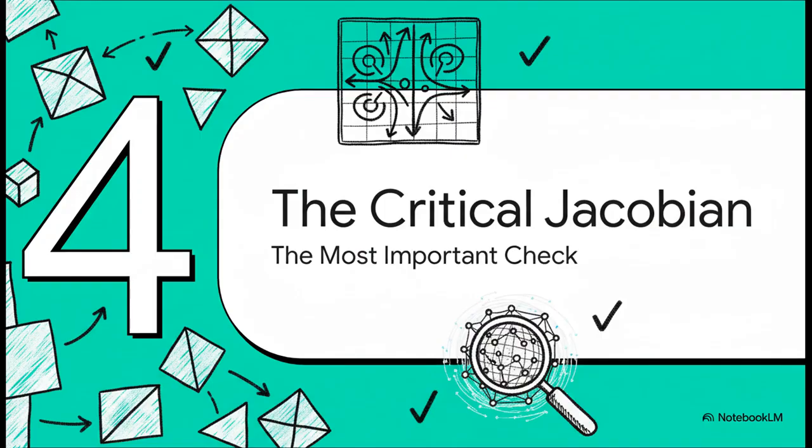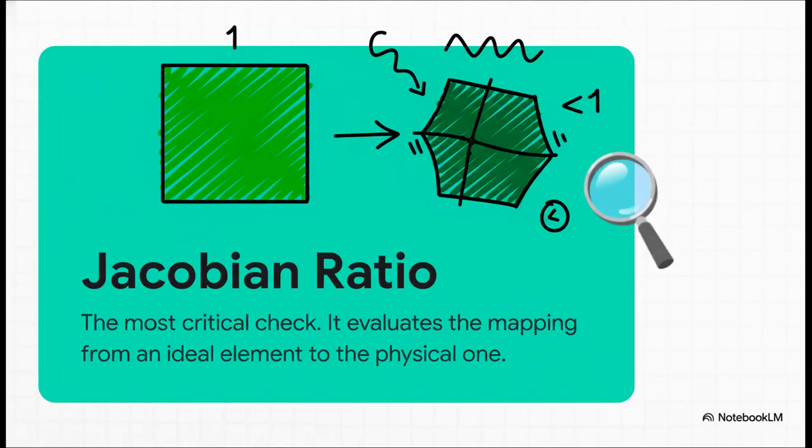All right, we need to pause and talk about the most important check of them all. Seriously, if you only remember one metric from this entire explainer, please make it this one, the Jacobian. Remember how we said the solver maps your real physical element back to a perfect one? Well, the Jacobian is the score that tells us how good that mapping is. A perfect score is 1. As your element gets more and more distorted, that score drops and drops.